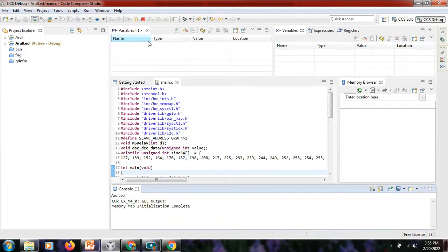Before that, you have to connect the audio jack into the audio output of the microcontroller board. From the audio jack connected to the audio output, the other end of the audio jack has two wires, that is positive and negative wires. Positive wire connected to CRO positive, negative wire connected to CRO negative, and you get that waveform. I don't have a CRO to show you the output, so you will try, and you'll get that output on your microcontroller board and then CRO.